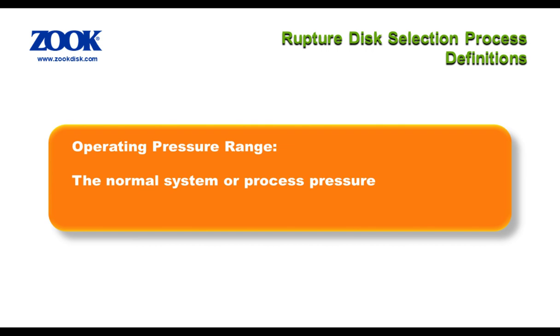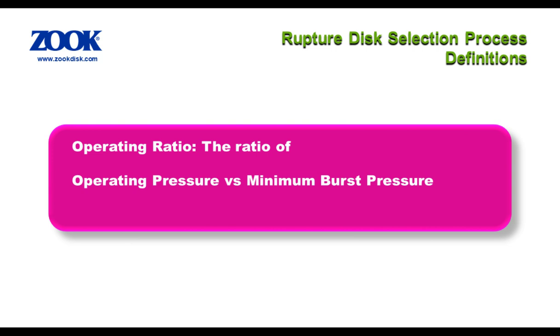System operating pressure is the normal operating pressure range the disc will see in service. The disc maker needs to know this to be able to choose the correct disc model. For example, some basic discs cannot tolerate operating pressures close to the rated burst pressure. Other designs may require extra components to withstand vacuum conditions.